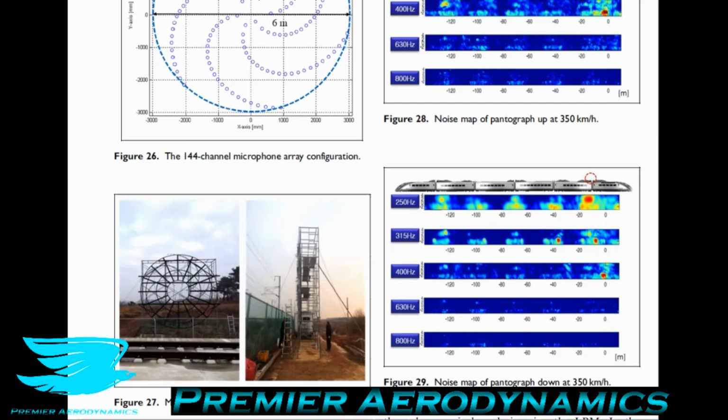But then when you put them together, you're not going to expect to get the superposition of these two spectra, because you're going to have the upstream effects impacting the downstream cylinder, and it's going to change that noise propagation as well. Also, even the downstream flow physics might affect the upstream flow physics, and that's going to change that too. This is called a secondary effect. So you can't get an entire picture of what's happening just by measuring something while removing another object, and then vice versa. You have to look at the secondary effects as well. And to do that, you can do something called a design of experiments, where you carefully plan your experiments to look into the primary and secondary effects based on different configurations.